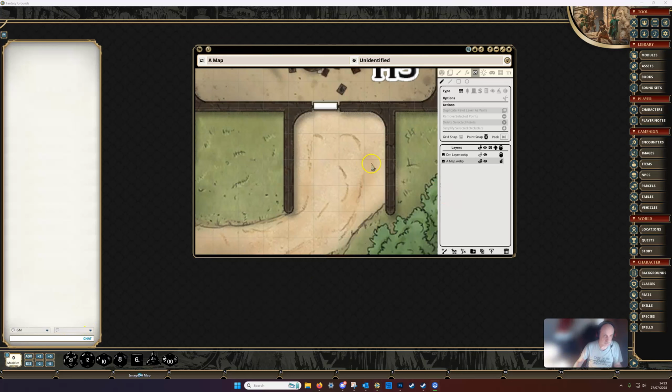So in order to draw straighter lines, we can select our line tool again, and this time when we start to draw, we're going to hold down the shift key, and when we do, you can see that the line is now snapping to 45-degree arcs.